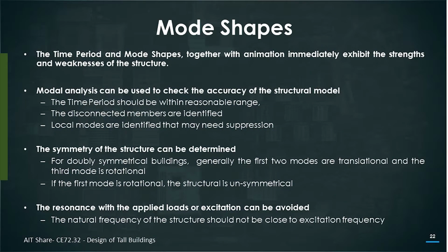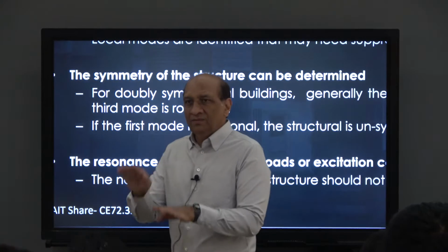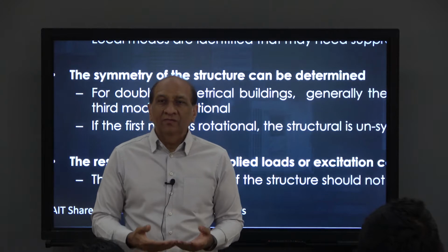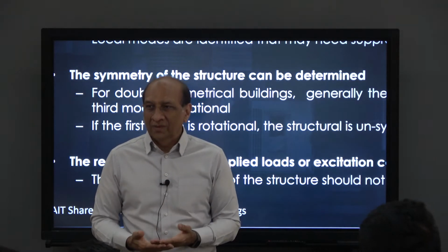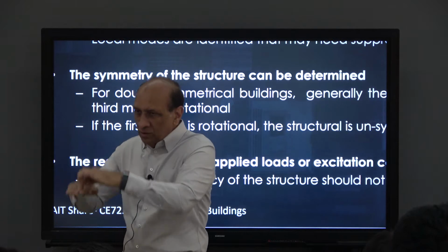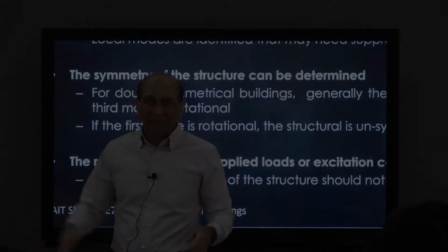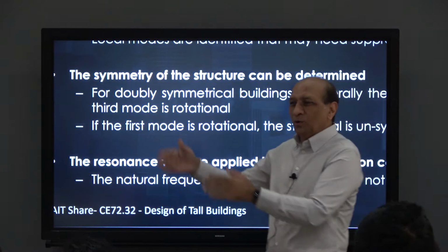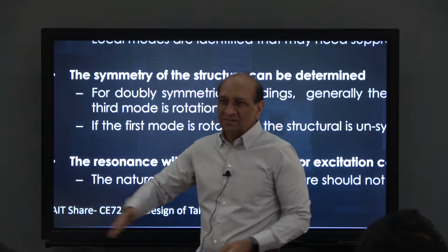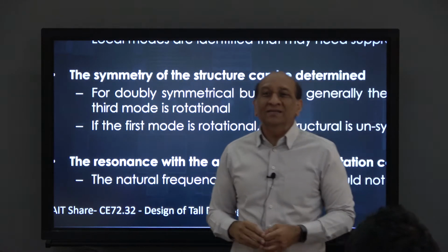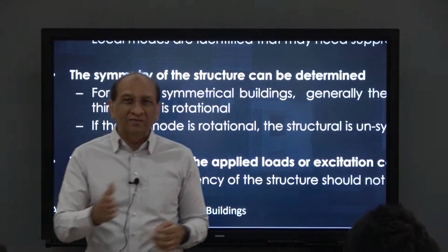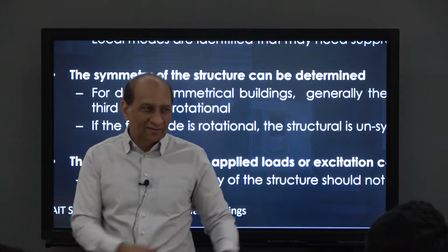Resonance is when the natural frequency or natural period of the structure starts to coincide with the force frequency. That means if the slab is going down and the load is also going down every time, it's like a swing. So if you're in a swing, you know how to go higher, right? You push when you are going this way, and you keep doing that in a systematic manner. You are utilizing the natural period of the rope and synchronizing with your force. That's why you can keep going higher.